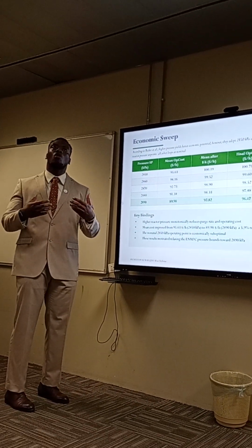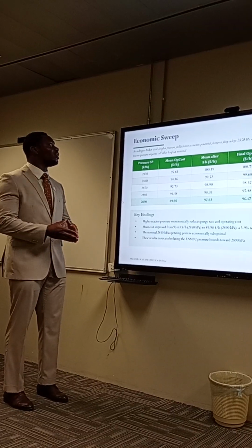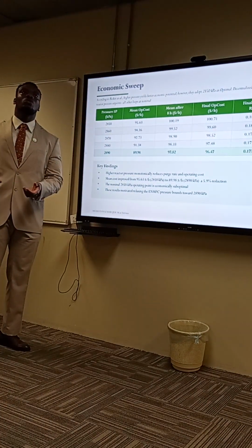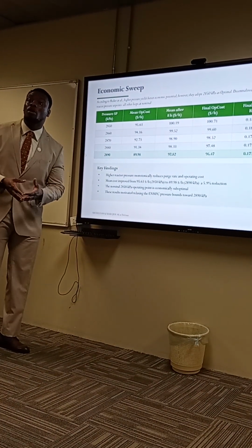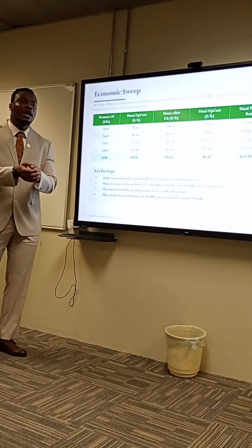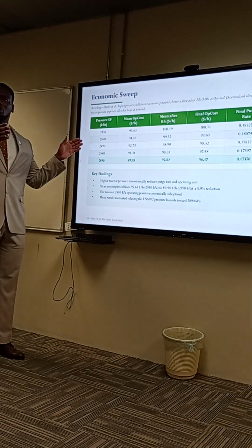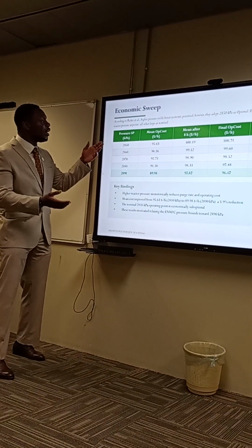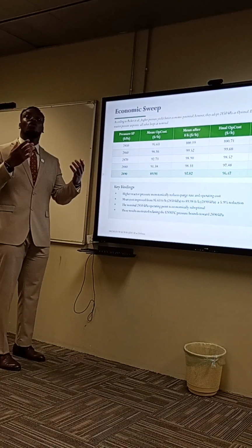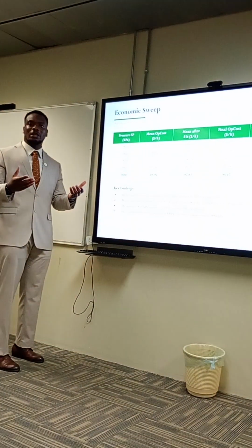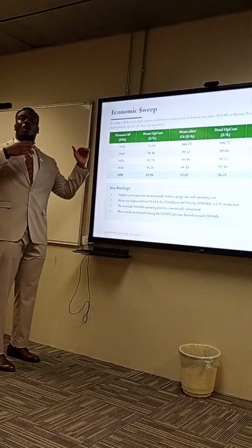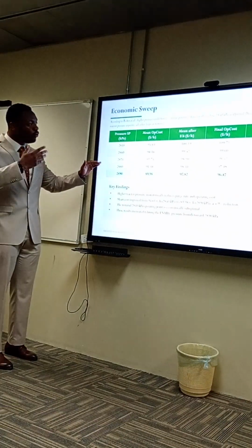Before tuning or running our EMPC, what we try to do is an economic sweep. An economic sweep is basically where you run an optimization based off your model, because you cannot manually calculate what the profit would be and get some optimal pressure range. So when we did that for pressure, although from the literature Rika already stated that when you increase the pressure, you get good economic standing, we did that first just to find out what the optimal pressure range would be, and to keep on moving that as well.